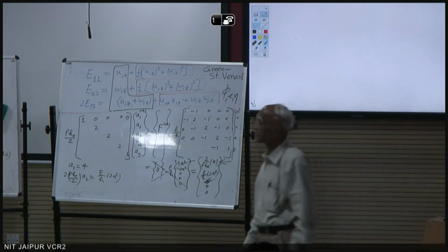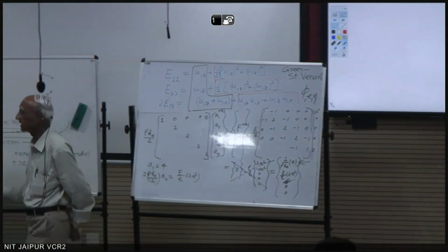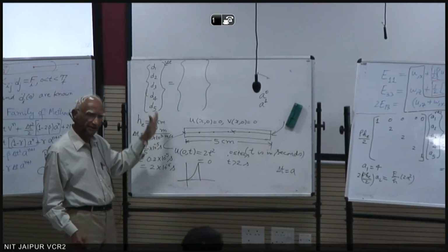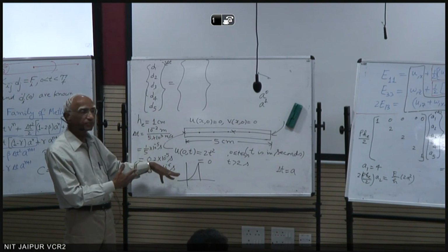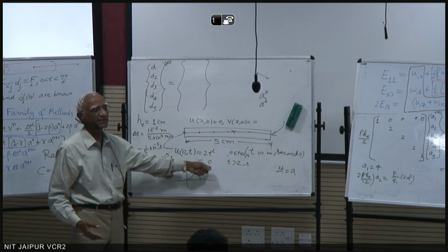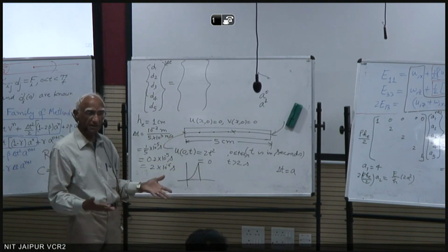And remember, this has a shock loading because we are suddenly making the acceleration 0. So what's happening is when you are pulling this bar, there's a stopper here. So once you pull it long enough, you cannot pull it anymore, because that's what this one says. The acceleration is 0. Then of course the displacement is 0 after that.